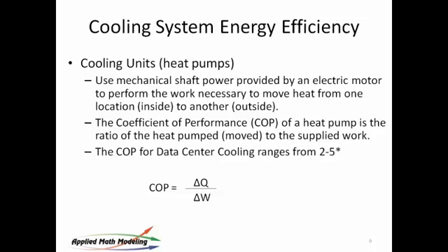Oftentimes you'll see chiller efficiency measured in kilowatts per ton, which has dimensions on it. The nice thing about COP is it's dimensionless. We're looking at the amount of heat being pumped compared to the energy required to cool the data center.